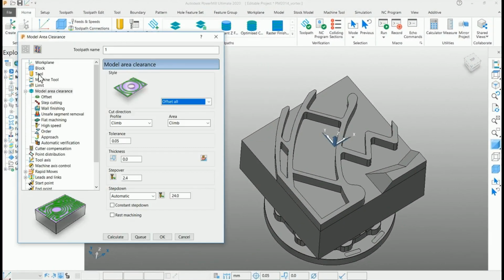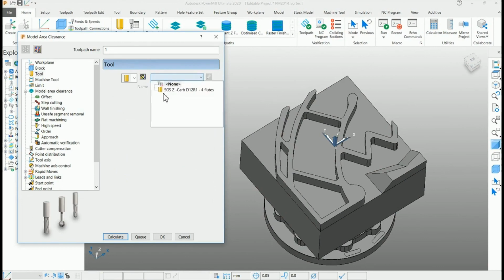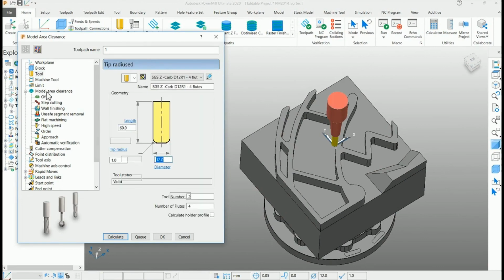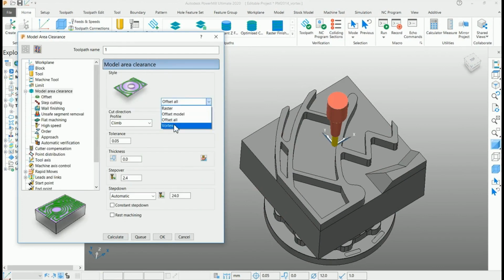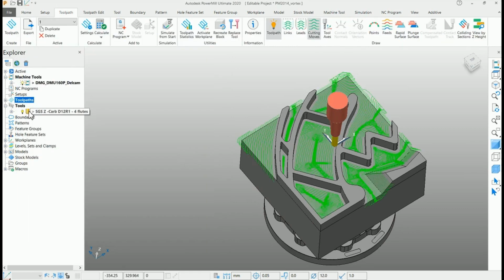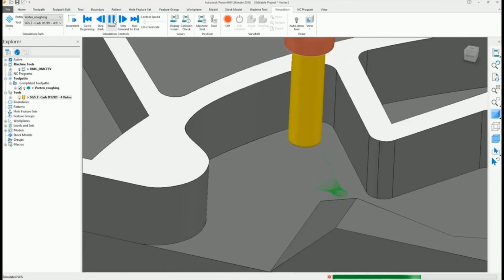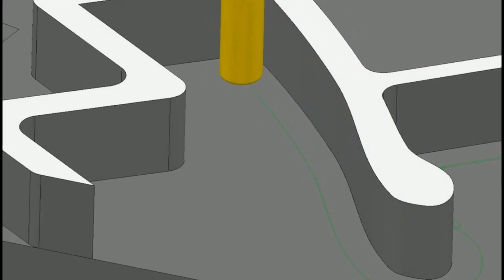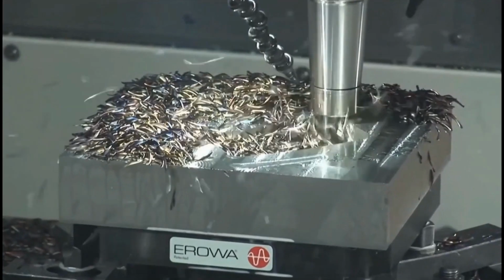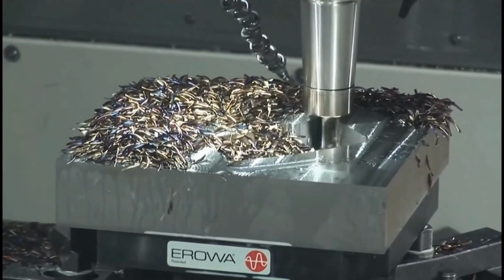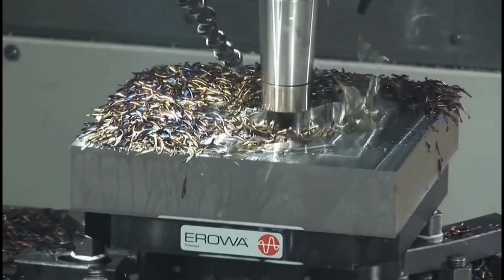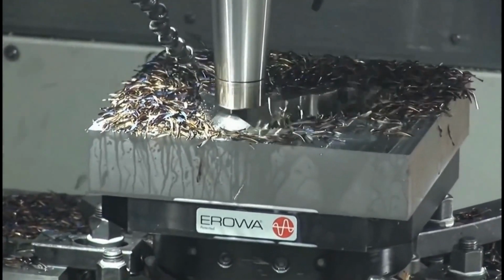Vortex is a high-performance roughing technique that allows us to run with much deeper cuts and much faster than the traditional roughing techniques. It cuts the material in controlled engagement instead of constant engagement, particularly in corners. It takes 4 times the diameter of the solid carbide cutter as depth. The entire tool path never exceeds the step over value, so the tool is never overloaded.